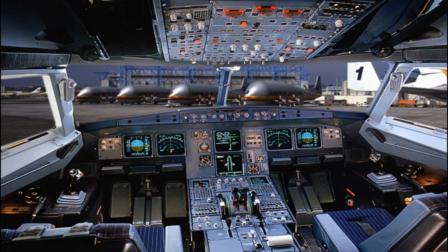Like the long-range LR, the Electronic Instrument System EIS of the A320 consists of two subsystems. The Electronic Flight Instrument System EFIS with two PFDs and two NDs, and the Electronic Centralized Aircraft Monitoring System ECAM with an upper and a lower display unit. The symbology, the color coding and the philosophy are similar for both aircraft. There are just some differences that we will cover in this module.